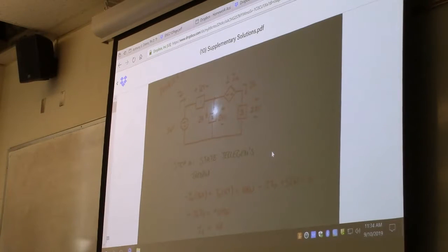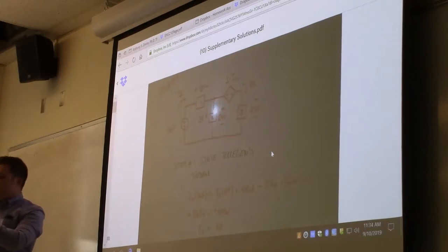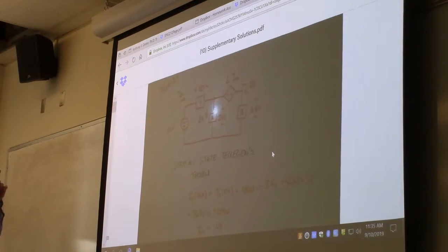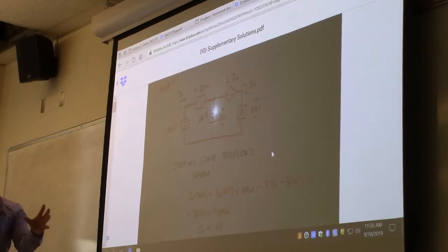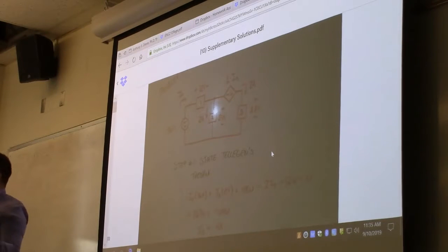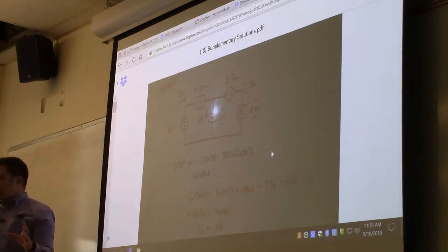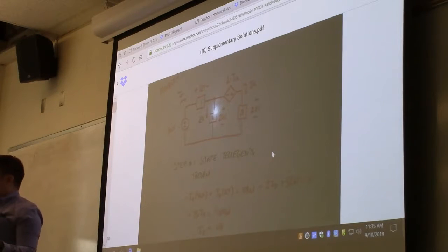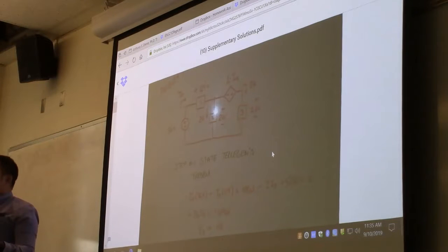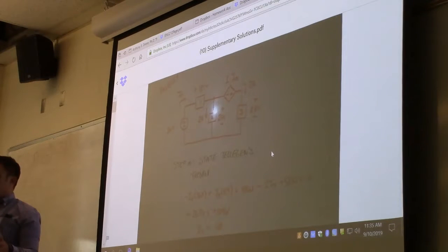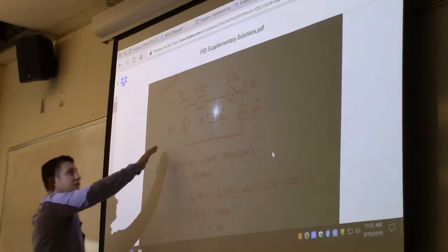That's not the reason. So let's look at the voltage and the current independently. What is the voltage across the terminals? It's 1 times Ix. Take that value, set it to the side. What is the current flowing through it? It's 2 amps. But it's flowing in the opposite direction of the passive sign convention, right? It's flowing from the negative to the positive terminal. So that's the reason why there's -2. Has nothing to do with the direction of this over here.